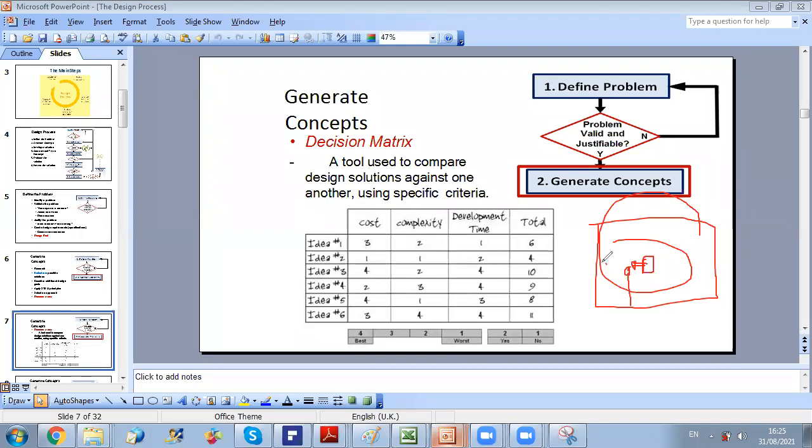Because when you recirculate air, already the temperature of air is relatively low, so it will not take you a lot of energy to cool it to, let's say, 14 degrees if you want to enter it at 14. And the temperature of the room is, let's say, 24, for example, okay? You have only a difference of 10 degrees. While if you want fresh air from outside, let's say you have a temperature of 35 outside, then you should cool from 35 to 14, which is on the cost level, it's very high.